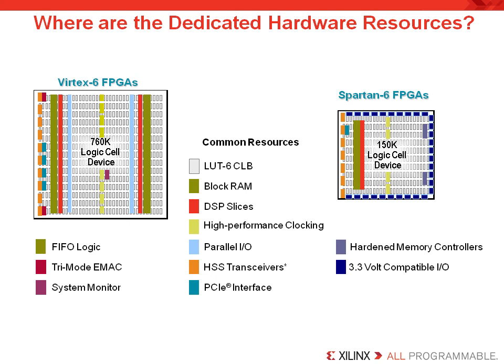This is equally important when you use area constraints to place CLB logic near your chosen pin assignments and dedicated hardware. The key dedicated hardware resources include clocking resources, block RAMs, DSP slices, high-speed serial transceivers, PCI interface blocks, dedicated memory controllers, and tri-mode Ethernet MACs.